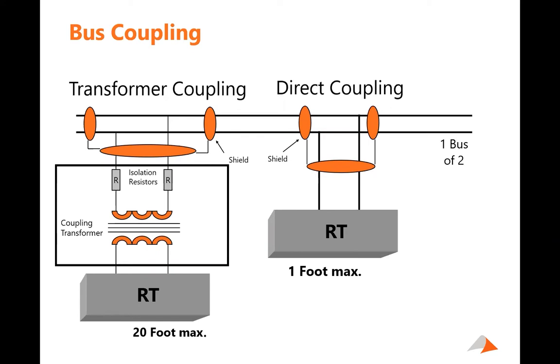I've seen the data buses, by the way. The standard when it first came out defined that the data bus could be as long as 300 feet. And then in the B version, they took that out. Part of the reason for that is that you can actually go longer. I have had over 1,000 foot data buses. And again, when you go far, you just have to be careful that you're going to affect the amplitude of your signals and your response times. Those are just things to keep in mind.